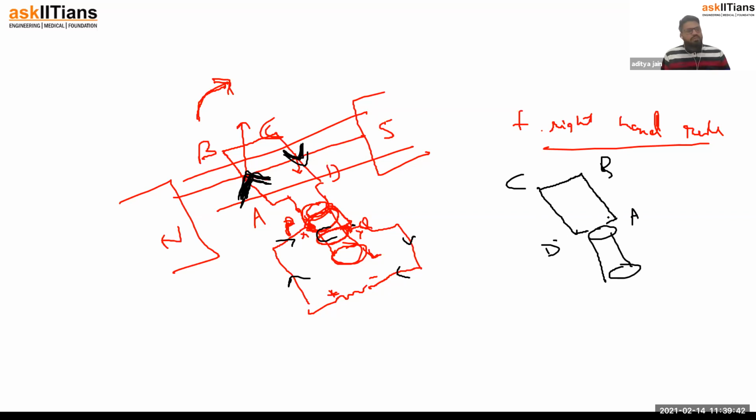Now if you see, the rotation was clockwise. Now the arm AB will go downward and CD will go upward, if you can observe. Because initially AB was this, CD was this. The rotation was like this, AB moving upward, CD going downward. Now after half rotation, this is CD, this is AB. Now CD will go upward and AB will go downward to move in the clockwise sense.